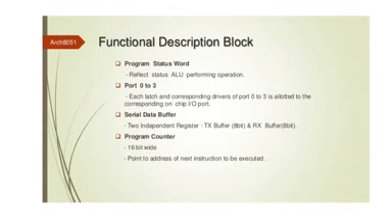Next, after that I have the auxiliary carry flag. That is at the D6 bit, and the carry flag at the D7 bit. Auxiliary carry is set whenever you have a carry from one nibble to the other nibble, from the 3rd bit. Next, the carry flag. Whenever you have a carry from the 7th bit, then this carry flag will be set.